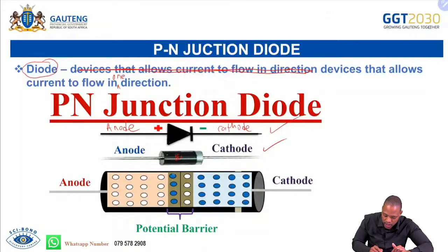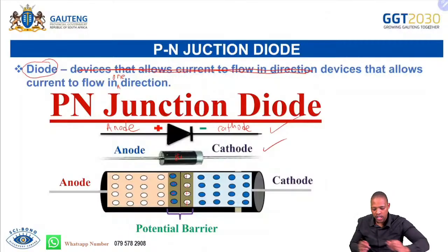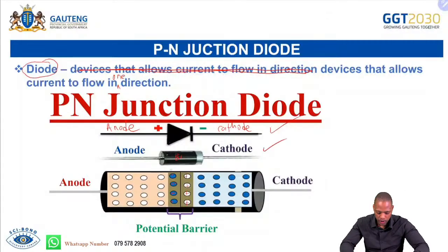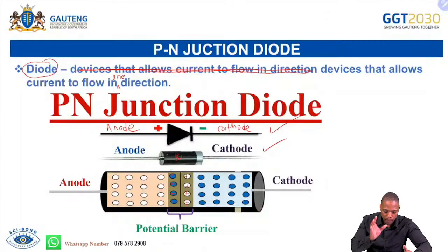And when they do that, the first electrons that get there bring in these negative charges here, and leave positive holes this side. But these electrons are now trying to cross and go across. These electrons are now repelling them. Now we have that depletion region that we are talking about. That is now causing our PN junction diode not to work yet. Okay, let's say it is not working yet.